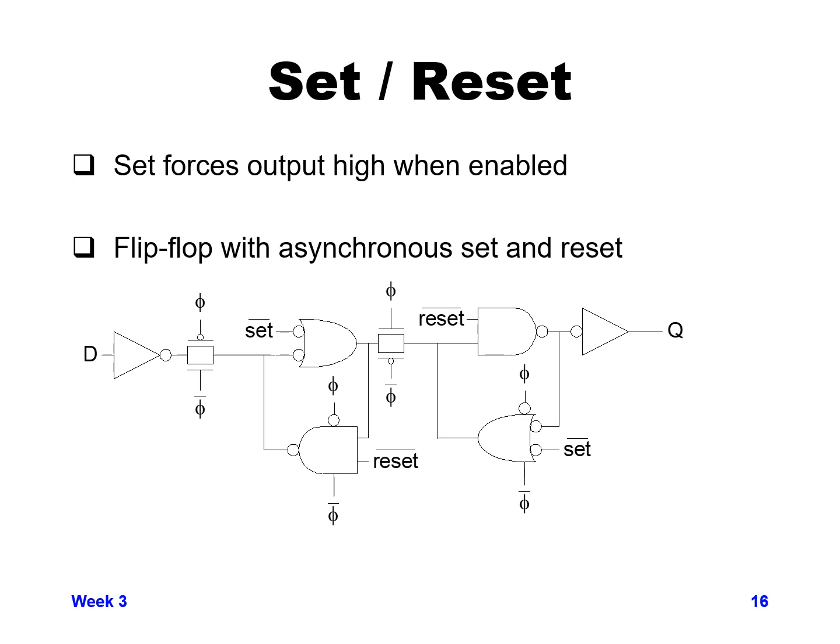It gets a little bit more complex, and you're just replacing different inverters with NAND gates or NOR gates being driven by either set or reset bars. So in each case, it causes a little bit of increase in the size of the master-slave flip-flop, but the overall structure is the same. So it's not an egregious amount of growth in order to get this functionality. In practice, there's usually relatively few master-slave flops that you might put set and reset on, but there are occasions where you need it in your circuits.